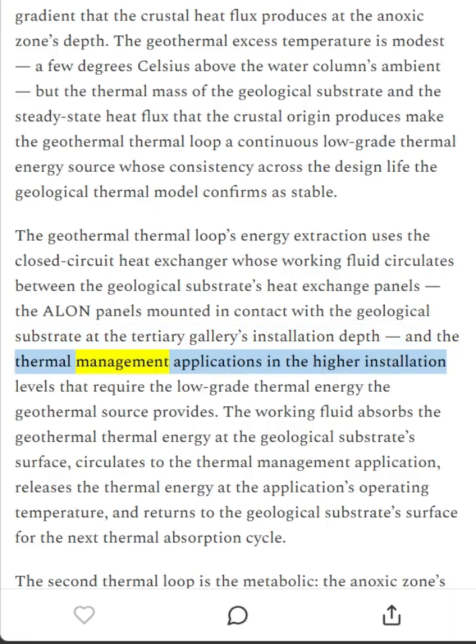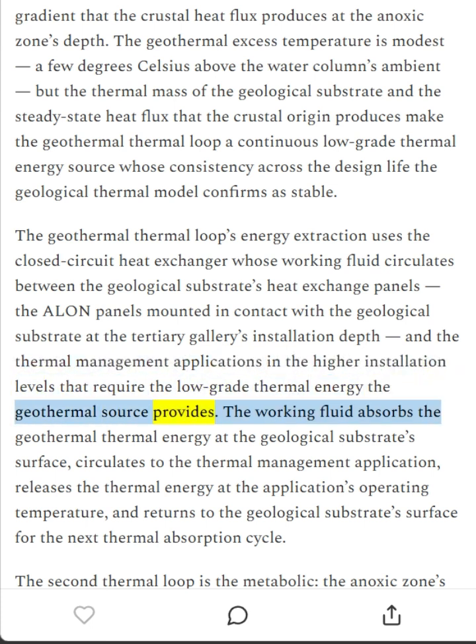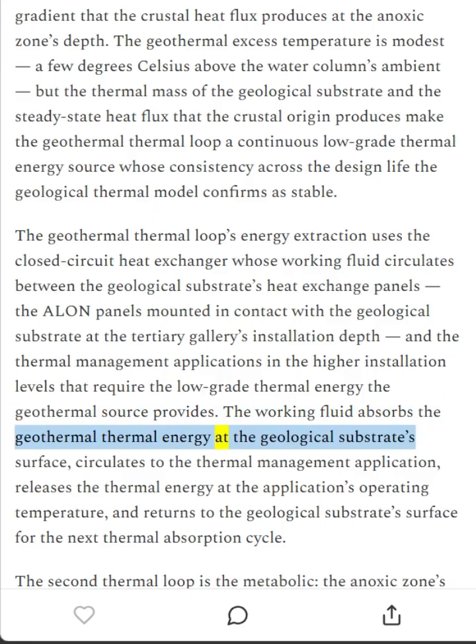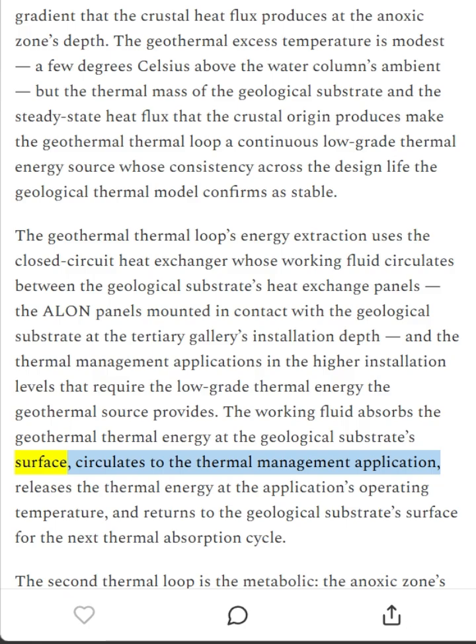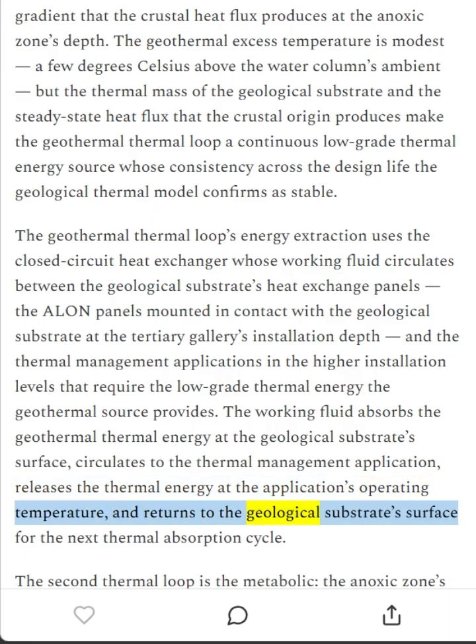and the thermal management applications in the higher installation levels that require the low-grade thermal energy the geothermal source provides. The working fluid absorbs the geothermal thermal energy at the geological substrate surface, circulates to the thermal management application, releases the thermal energy at the application's operating temperature, and returns to the geological substrate surface for the next thermal absorption